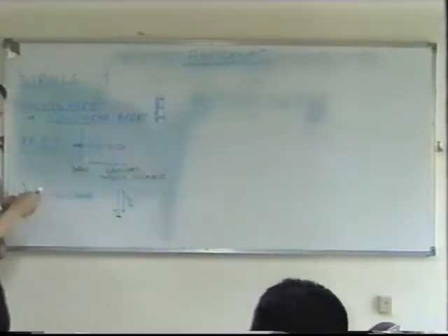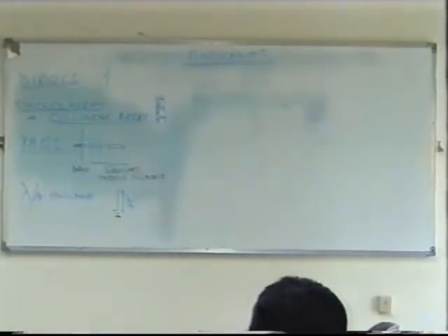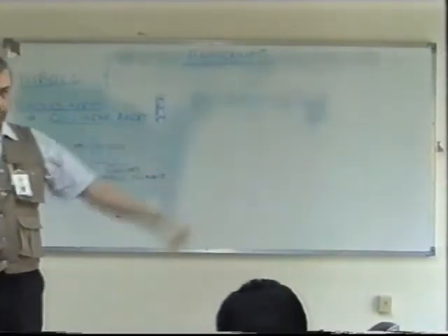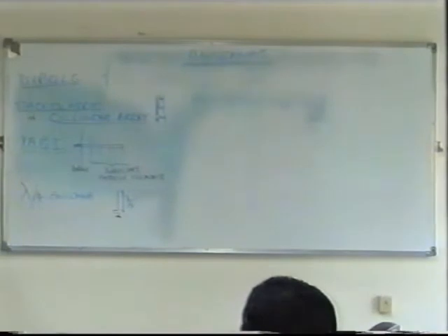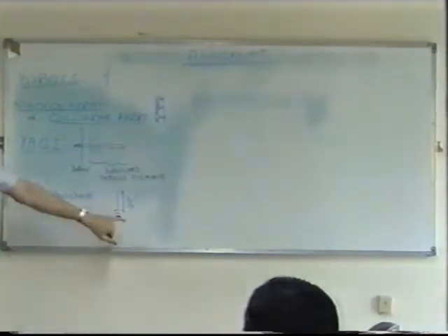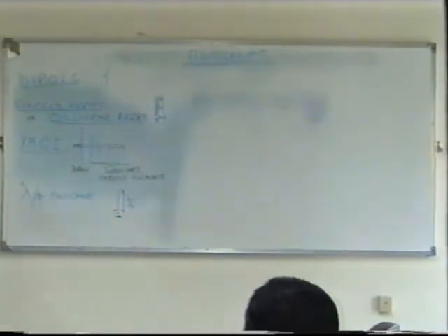Now, why do we do that? Well, it does save space if we're using lower frequencies, because lower frequencies mean longer wavelengths. So it saves space. Also, you might use this sort of arrangement on a car. It's more convenient to use this type of arrangement on a vehicle, perhaps, particularly at VHF.